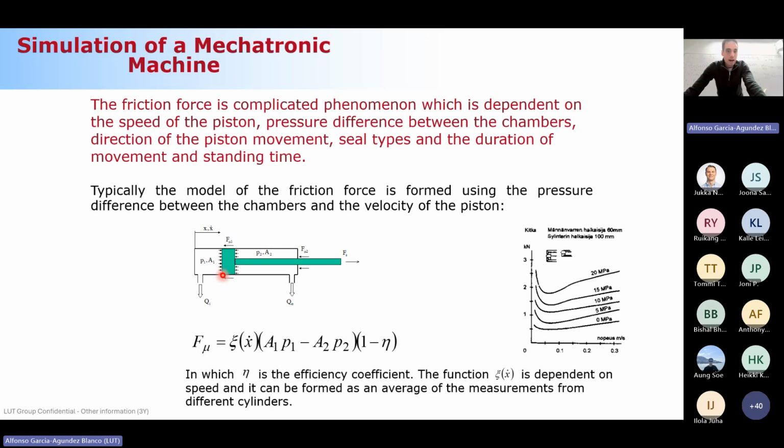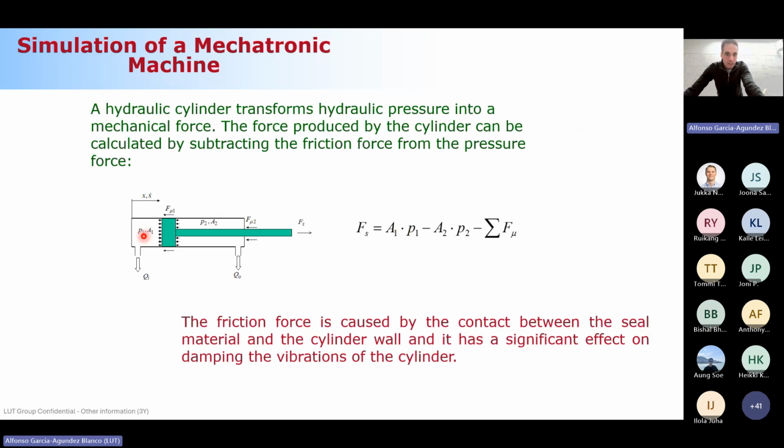You can see here a force balance in your cylinder, okay? So basically, this distributed force here is the pressure in the piston side. So the net force, the total force, would be A1 times P1, which is this expression here, A1 P1, okay? On the other side, one question that I have for reviewing for the exam: the acting surface in this side, which geometric form does it have in the piston side? It is a circle, right? So this A1 would be the area of a circle.